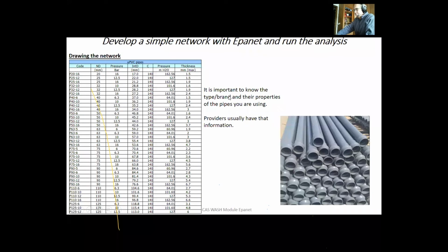And so now you have your system set, and like I was telling you, you might go to the supplier in Idlib or I don't know in Aleppo, and you might ask what type of pipe do you have. He will tell you, I have only PVC, I have only PA of this dimension. Important is that you work with the right internal diameter, and additionally you also check the maximal pressure that those pipes can support.